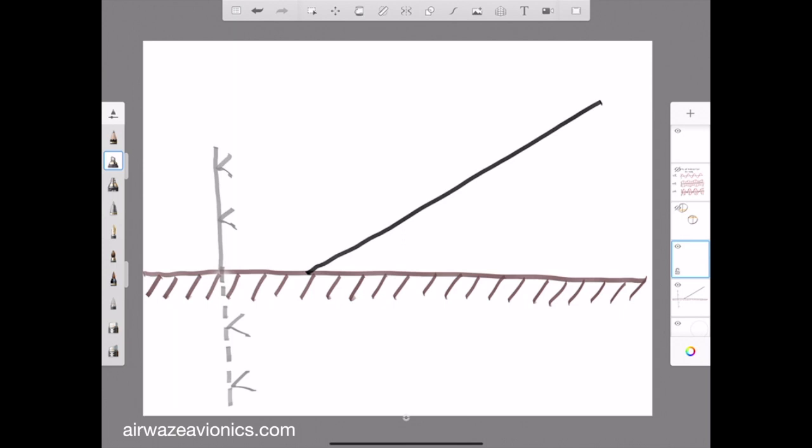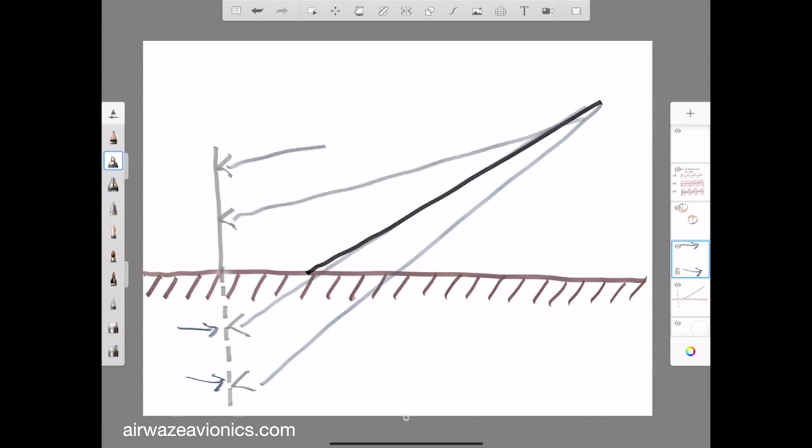The radiation pattern formed by these 2 antennas can be conceptualized as if there were a set of imaginary image or mirrored antennas radiating from inside the ground plane. However, the pattern is actually formed through spatial interference between the direct and reflected beams from the real antennas above the ground plane. The reflected beams are bouncing off the ground surface, so for the null reference system, it stands to reason that a flat and uniform ground plane is required.